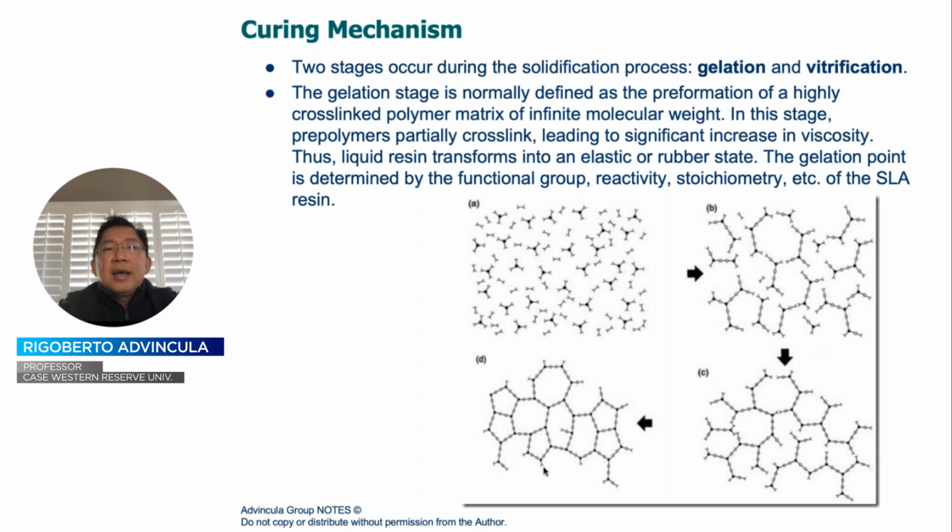So let me digress here first by emphasizing that in a cross-linking process, what you essentially have are cross-linkers or gelators or vitrimers even that are able to react with its neighboring molecule to produce a random order rather of network structures which then grows over time. In fact, it is very well known that in a curing mechanism for thermosets such as epoxy or urethane, a gelation step occurs first, or rather a very high increase in viscosity, which then leads to fixation of these reacted links or cross links into a very static structure such that leads to a thermoset or a hardening. So you have a transition from a viscosity to a modulus driven or bulk process.